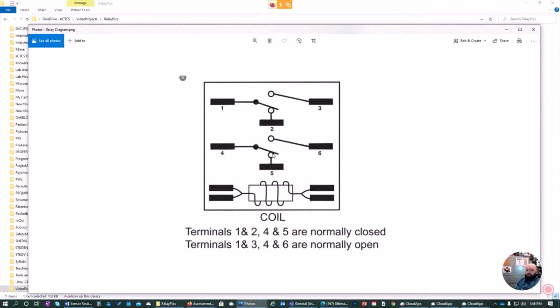Control boards have both high and low voltage. That's different. Thermostats do not. Safeties like pressure switches do not. Gas valves do not. It's only things that have switches for high current, like contactors, relays.